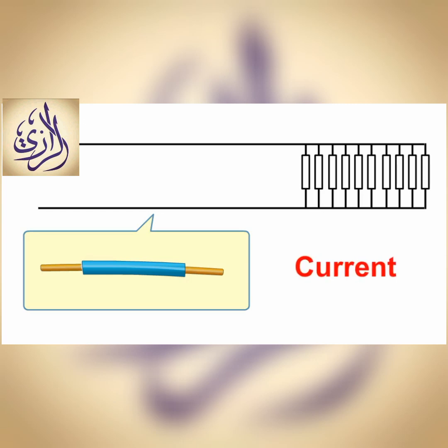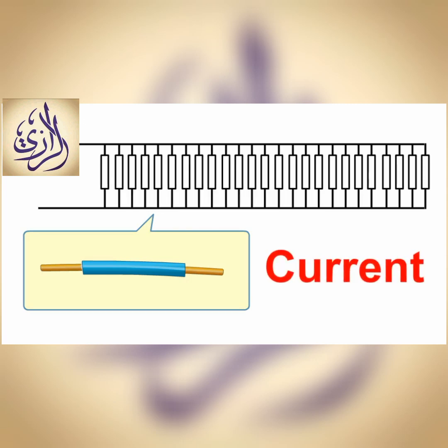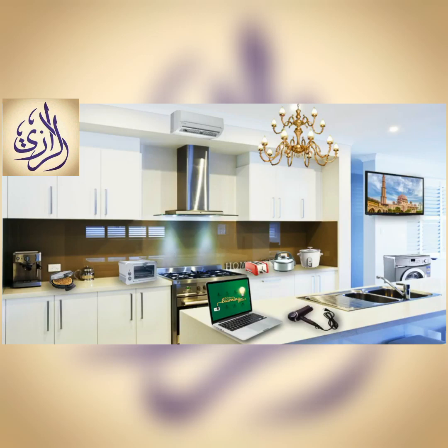As more electrical components are added in parallel, the effective resistance decreases considerably, resulting in a large surge of current. This will produce a lot of heat in the connecting wires, causing the insulation to melt and burn. In the past, this was not a big problem because there were not many electrical appliances in a common household.